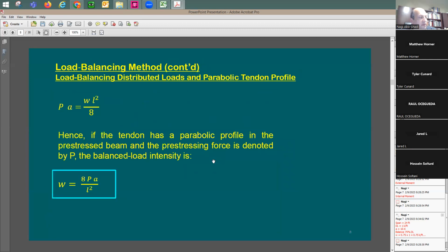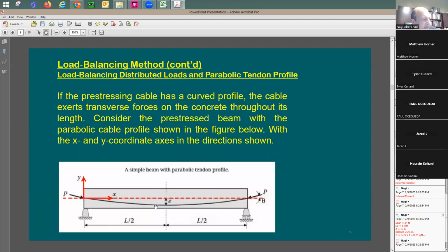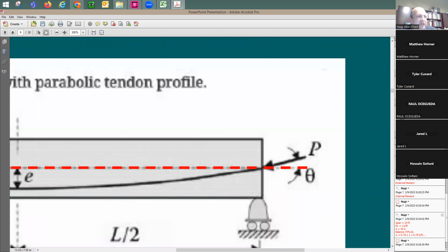Okay. So at the bottom, I'm going to put the cable here. You see here how it goes, then goes to the top. This drape also goes to the top, because I'm expecting uniform load here. So, okay. And this comes here to the centroid, the middle span. I'm going to have this e, the maximum. Look what happened here to the axial force. When I was doing the axial force in my analysis, I usually assume the axial force to be like this, correct? To be straight.